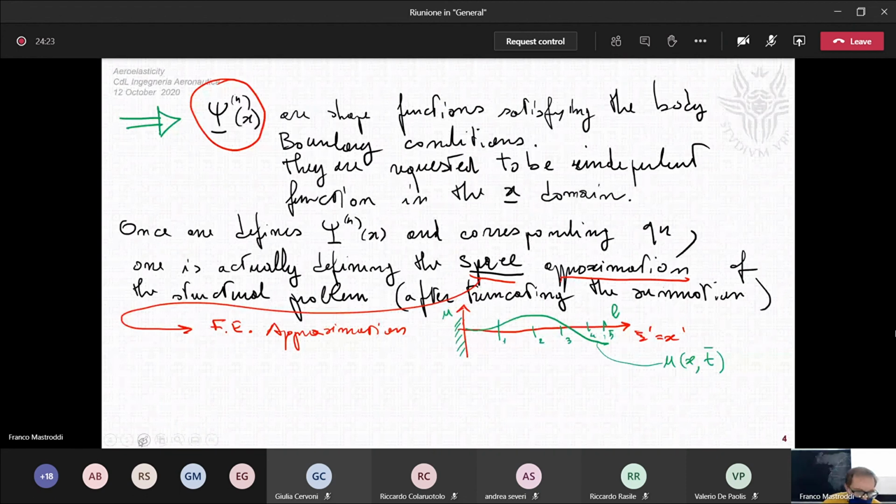Okay? And introduce the following 5 psi functions. First one is psi1. Psi1 means a psi of x function of this type. This is 0, and then the value of the function at node number 1 is 1, and 0 at the other nodes.